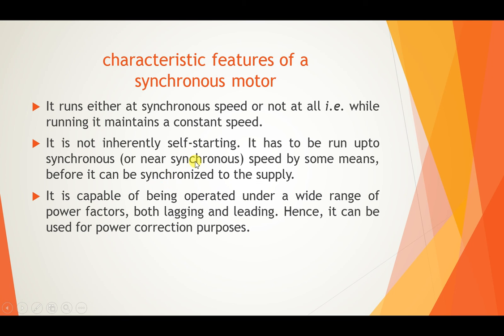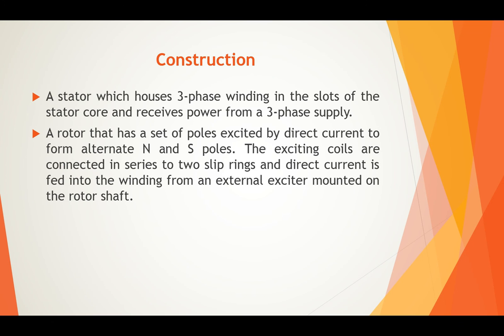We will study this in the coming slides, so you will understand how it starts. It is capable of being operated under a wide range of power factor, both lagging and leading. Hence it can be used for power correction purposes. So a synchronous motor runs at a synchronous speed, it is not self-starting, and it is used for power correction purposes. Now let's see its construction.